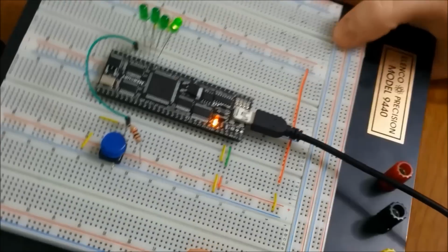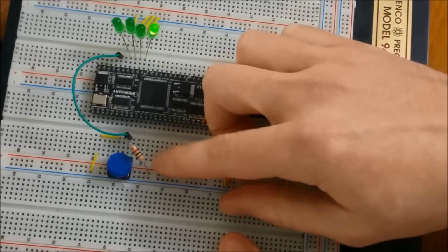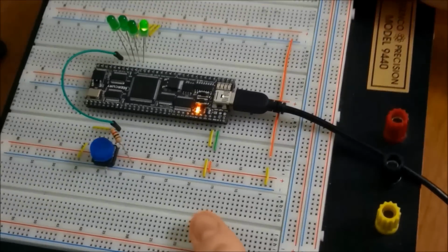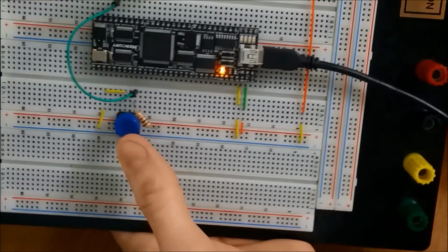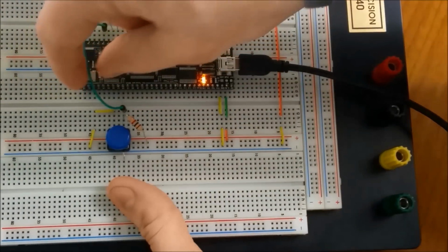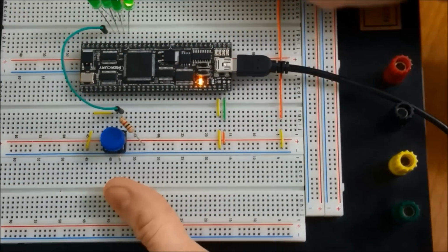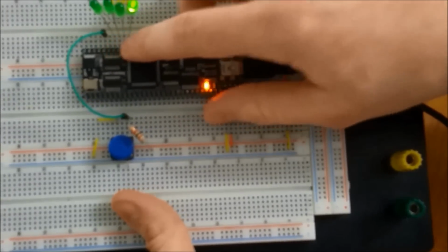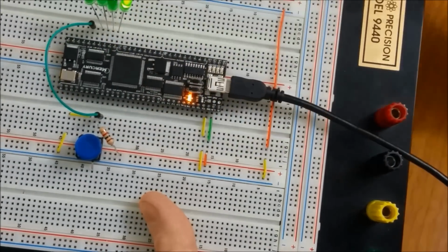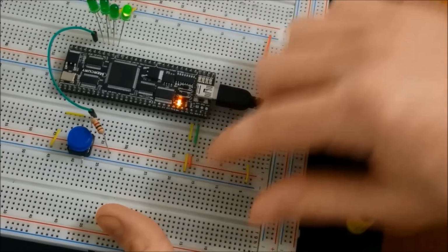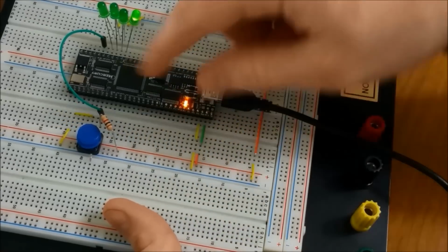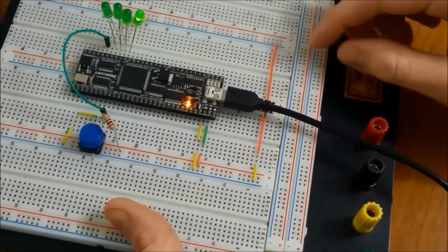I would have shown you how to build the circuit, but connecting LEDs and setting up a button with a pull-up resistor is pretty easy, so I thought I would leave that up to you. This button has a pull-up resistor here, and when it's pressed, it will pull the node down to ground, which is this green wire, connected to pin 6 on the Mercury board. These LEDs are connected to the 4 inputs and outputs on the Mercury board as well. And then I just have some wires that connect from the 3.3 volt node here, and the ground pin from the FPGA connected to the rails here and here.